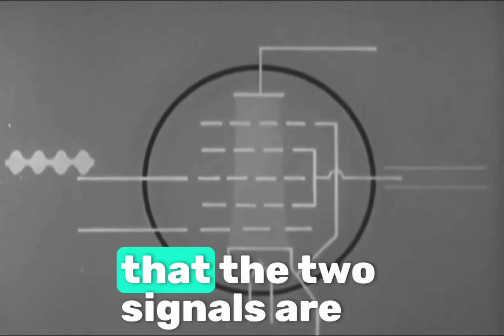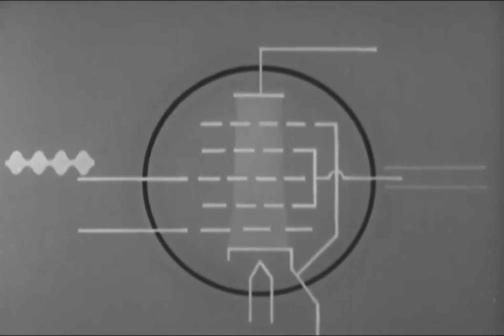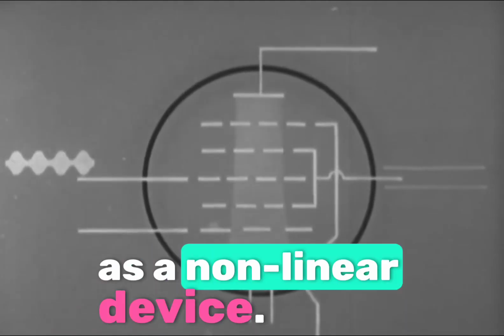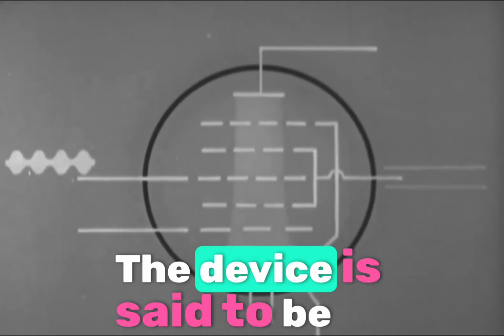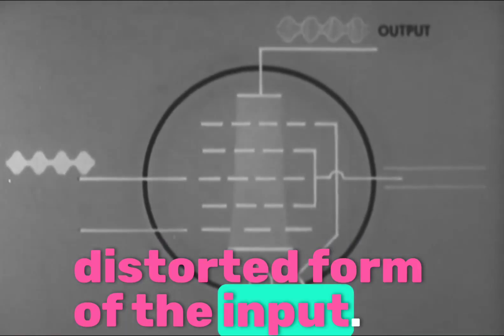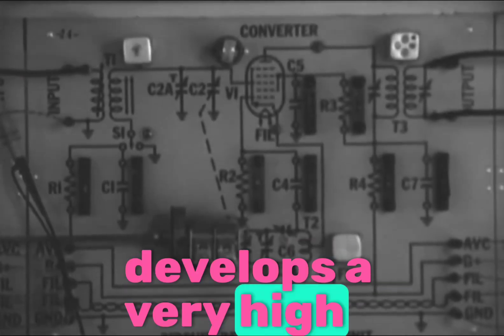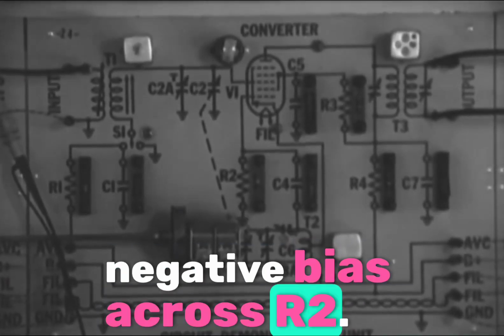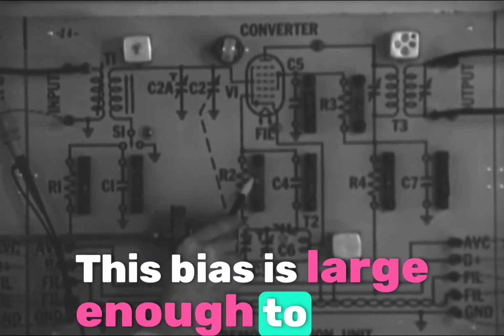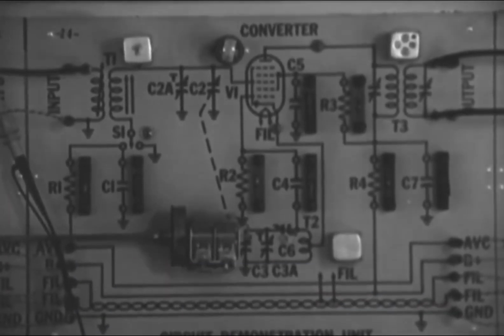You may well imagine that the two signals are thoroughly mixed together. This converter tube is acting as a non-linear device. A device is said to be non-linear when the output signal is a distorted form of the input. The oscillator circuit develops a very high negative bias across R2. This bias is large enough to ensure that the tube operates on the non-linear portion of its curve.